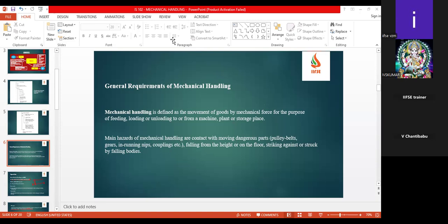So again, Chitti Babu, what will happen is the EOT cranes have different capacities, 5 ton, 10 ton, 20 ton. Is it possible to do a load test at 20 tons every time? Do we have that test block? No, sir, we don't have, sir. Again, that is the question mark. So there are some practical limitations with these calibrations also.